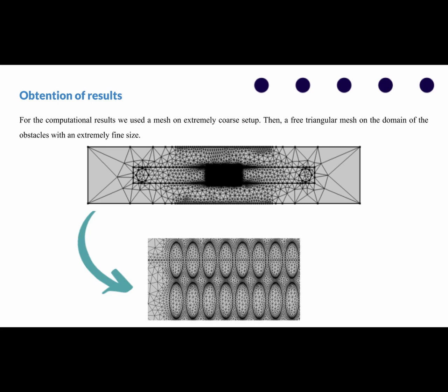It's not necessary to always have a small geometry size because if you have a small size, the computer will work more and it will take more computing time. So one of the strategies is to mesh with bigger size the parts that we don't care about, and with smaller size the part that we want to analyze.